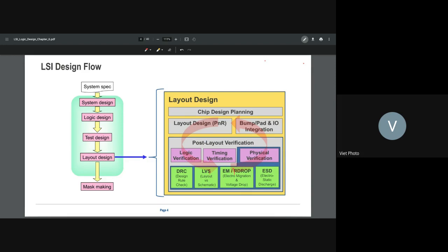They will calculate the electromigration. They will calculate so that if we have a width, the metal width, the via width needs to be larger than a certain number to make sure that over time, when we have electromigration, they will limit the current, because the current needs to be limited so that it won't inject or reject the electrons from the via, right?